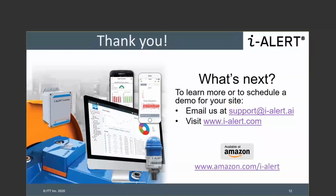And since the iAlert is measuring temperature, we recommend using an epoxy that has metal or aluminum chips inside to give good thermal conductivity up to the iAlert. You can also use that mounting base. It has dimples on it, which allow you to get on a curved surface as well. So you can also do a through bolt through the iAlert, through the mounting plate, onto a curved surface like a motor or some other centrifugal piece of equipment that you might have.